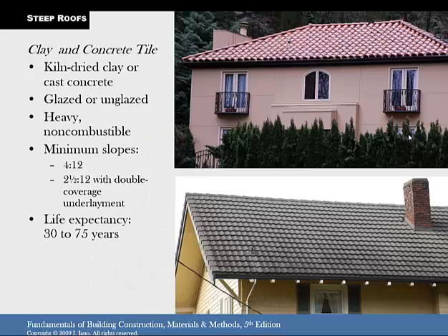Clay and concrete tile is another one. It's common, especially down toward Mexico and in Italy and all those areas, because they have an abundance of that material. But again, it's heavy, so you have to beef up your structure, and they can last from 30 to 75 years. But you have to be very careful with these, because obviously you can't really walk on these roofs, or you'll bust the tiles.